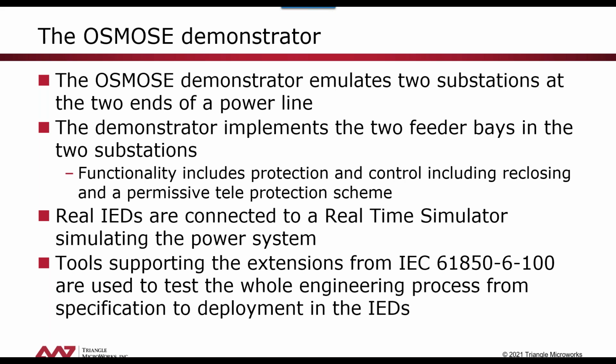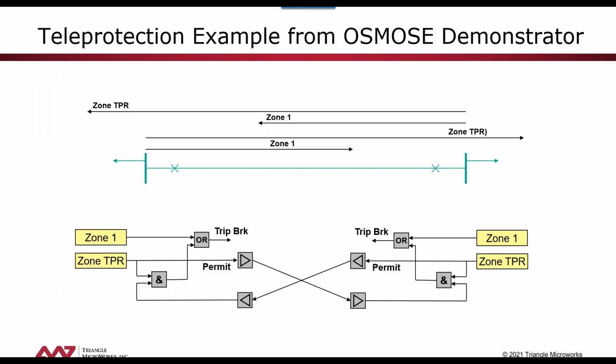We have real IEDs that are connected to a real-time simulator that simulates the power system. The demonstrator is set up in the laboratories from R&D Nester in Lisbon. Tools supporting the extensions from 61850-6-100 are used to test the whole engineering process, as Thomas has mentioned. One of the applications that we will later on demonstrate, and how we can simulate that, is a teleprotection example.